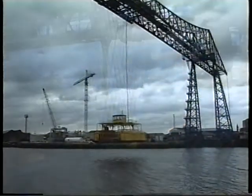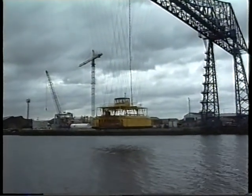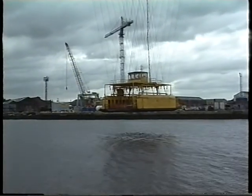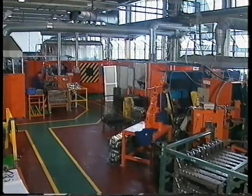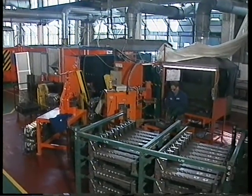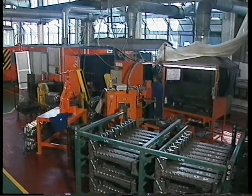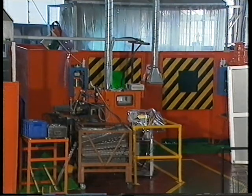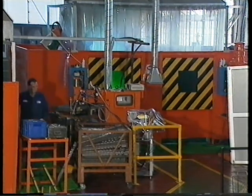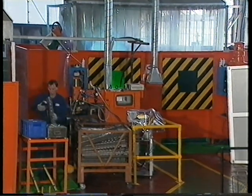As technology has developed, engineers have demanded steels with higher and higher tensile strength, together with adequate toughness. By increasing the carbon content of steel and providing the appropriate heat treatment, it was possible to greatly improve the material properties. However, the limit by using this technique was very quickly reached, and other means of improving the steel's properties were required.